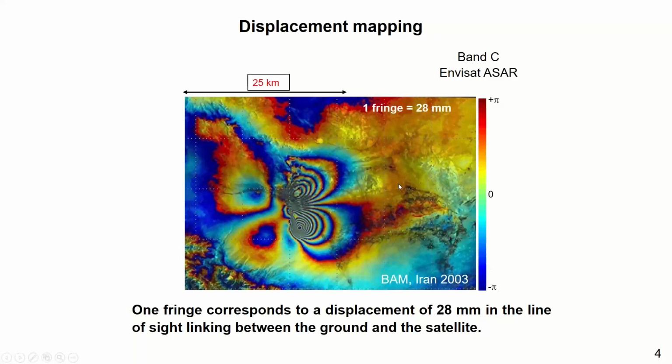And how can we know that when the phase is decreased, it will be going down or going up? Can I say is it sinking or is it rising? Because in this one we use the image from before the earthquake minus the one after the earthquake. So when the phase is going down, when the phase is negative, it means a subsidence. When we assume that one is the reference one, and this one is going down until here, exactly we are going down here about minus 17 centimeter.